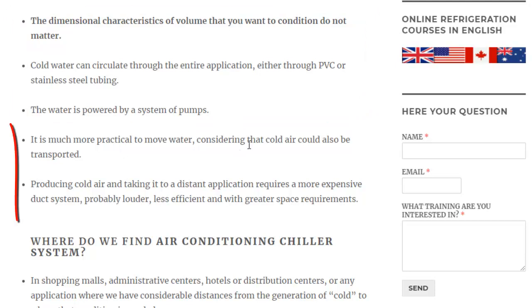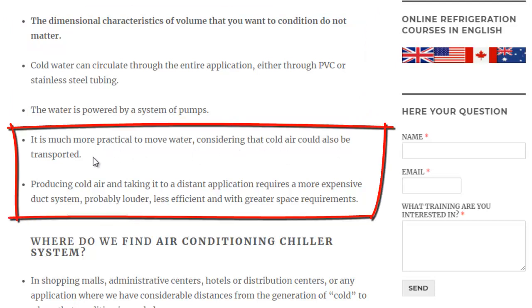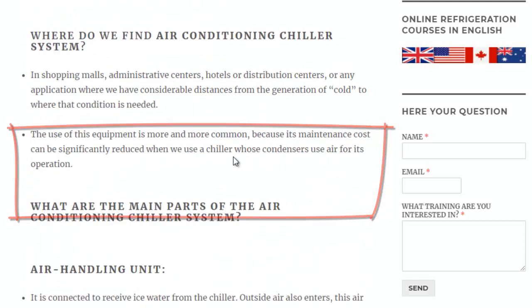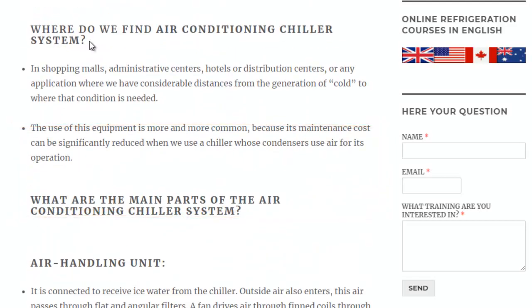It is much more practical to move water, considering that cold air could also be transported. Producing cold air and taking it to a distant application requires a more expensive duct system, probably louder, less efficient and with greater space requirements.